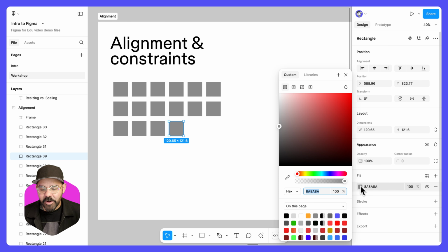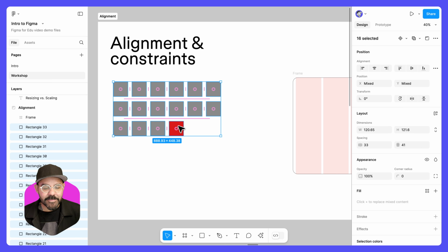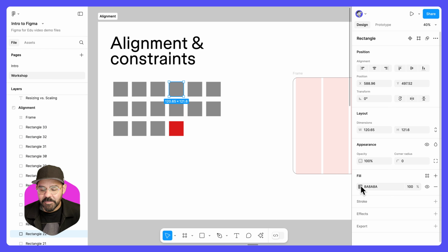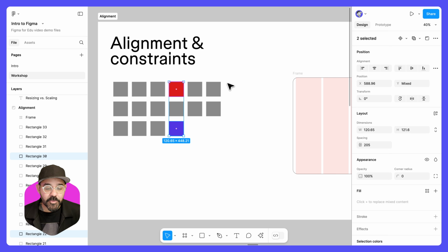So this will allow you to better space and adjust the elements that you're working with. Even if one of those elements is red, if one of those elements is different, you want to move it around, you'll see how it rearranges everything. If you want to swap it one for one with another object, hold down the Command key, Control key if you're on Windows, and you can swap it one for one with another object. If I was to make that object blue, you can see how this works, wherein I can just select both of these and swap them one to one, or if I select the whole thing and I hold down the Command key, I will swap the red one for the blue one.